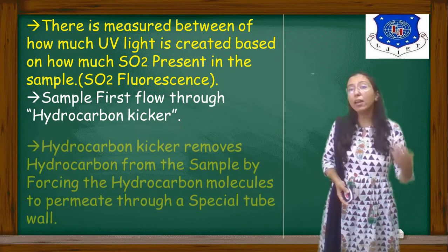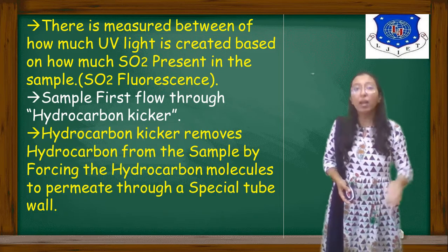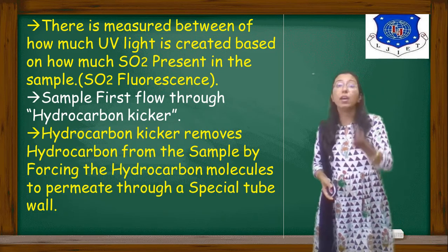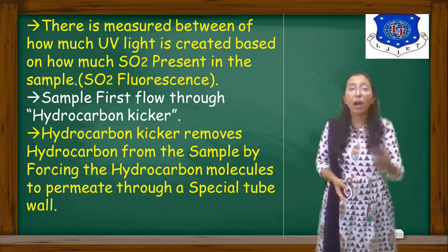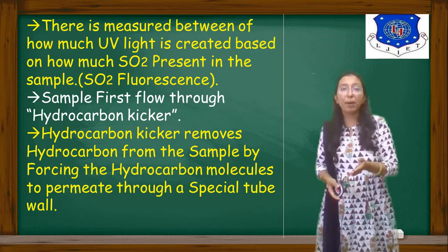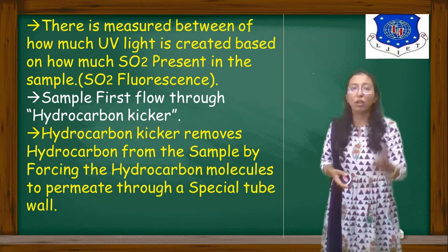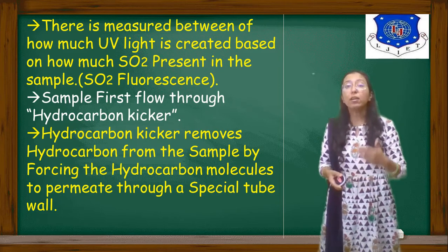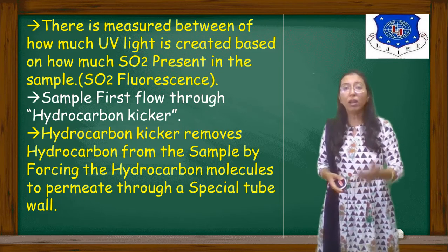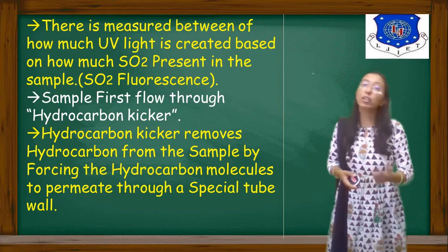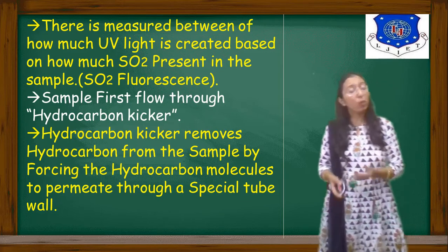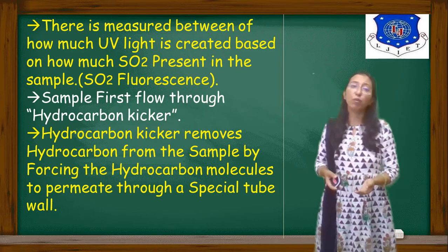Why do we use a hydrocarbon kicker? Hydrocarbon kickers remove hydrocarbons from the sample by forcing the hydrocarbon molecules to permeate through a special tube wall.